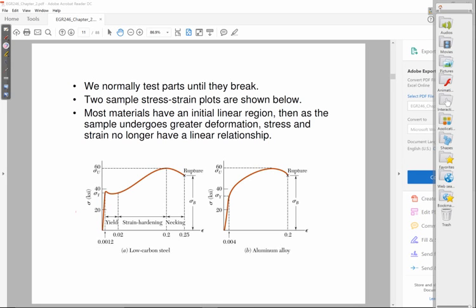So in the linear region, how much deformation is actually happening? Look how steep that curve is in the linear region, right? It means you have to apply very large stresses just to get a tiny amount of strain. So there are very little strains. There's very little deformation. And if there's very little deformation, what can you say about the change in the cross-sectional area? It's almost nothing. Okay?